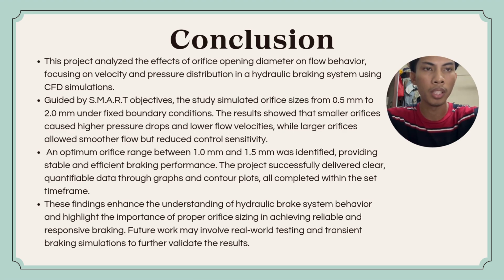Next, an optimum orifice range between 1.0 mm and 1.5 mm was identified, providing stable and efficient braking performance. The project successfully delivered clear, quantifiable data through graph and contour plots, all completed within the set time frame. Next, these findings enhance the understanding of hydraulic brake system behavior and highlight the importance of proper orifice sizing in achieving reliable and responsive braking. Future work may involve real-world testing and transient braking simulation to further validate the results.